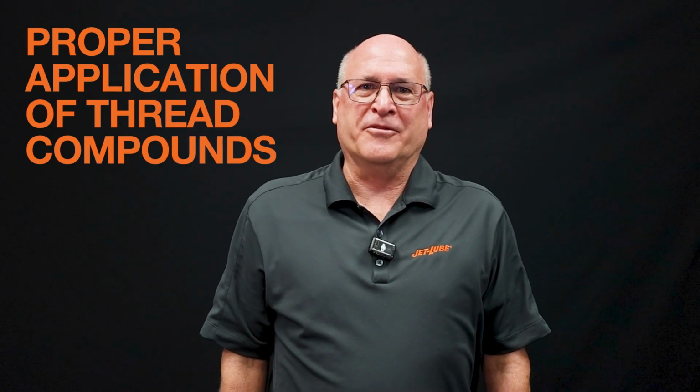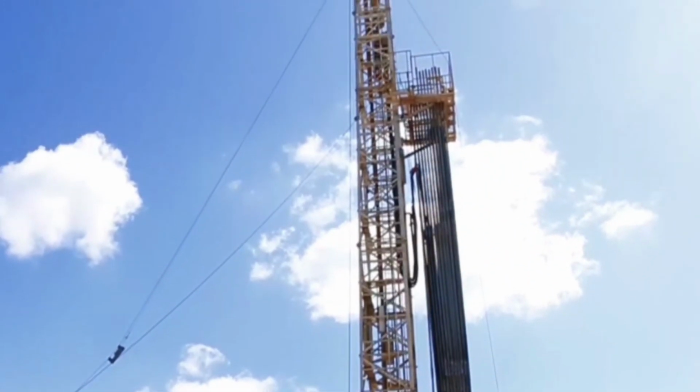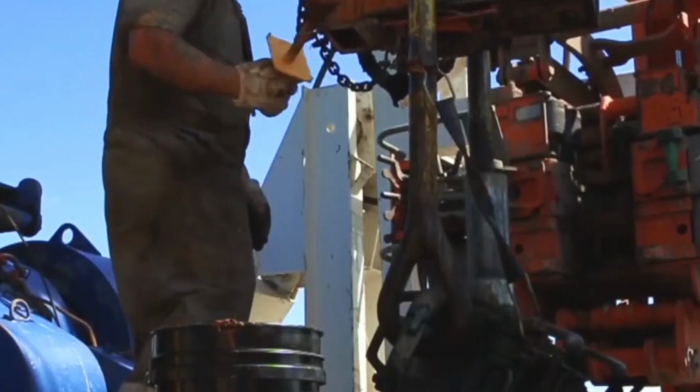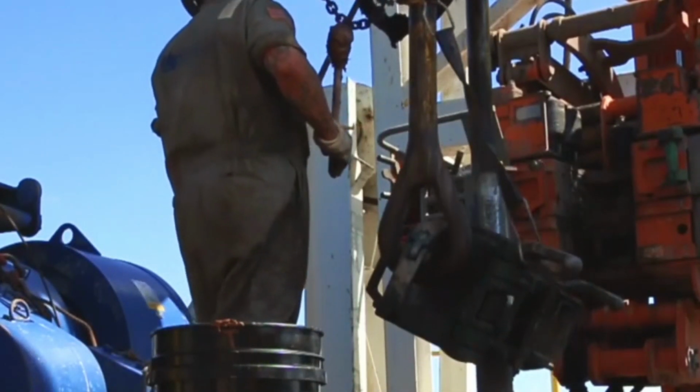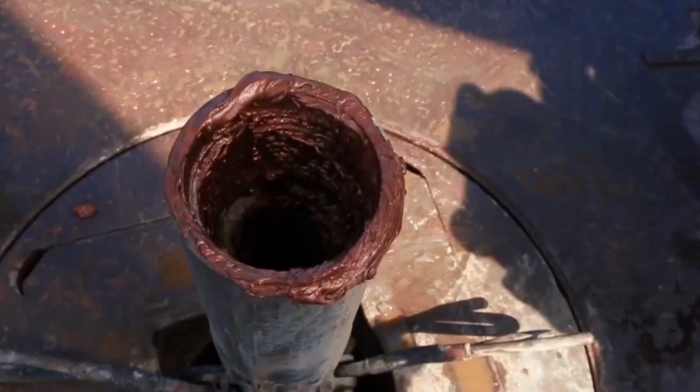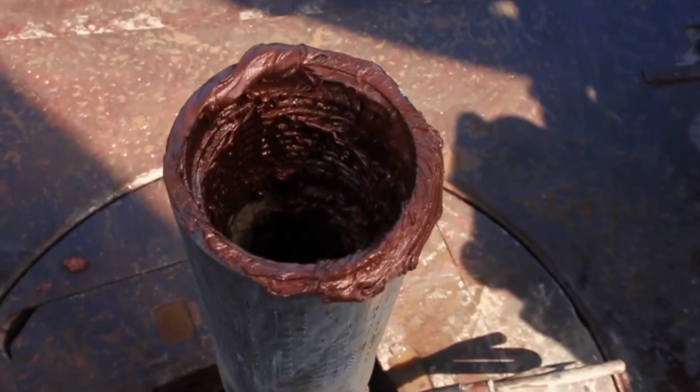Proper application of thread compounds. The proper application of thread compounds ensures effective performance. Stir thoroughly to reblend any oil bleed or settling of solids. Ensure the contact surface is clean, dry, and free of contaminants. Select the correct compound. Avoid using drilling compound on casing and tubing connections unless using a hybrid compound.